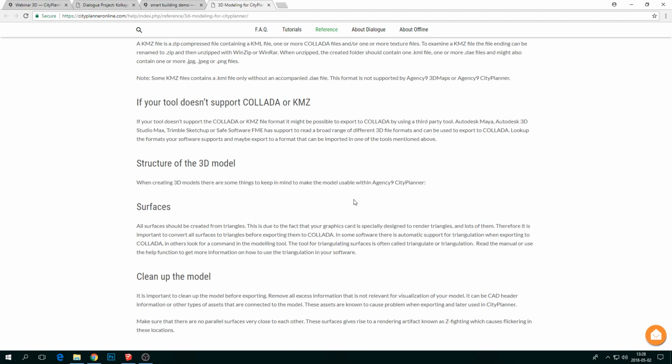So, a quick summary of what we've been discussing, and again, if you have any questions, feel free to ask them in the chat window or contact us after this webinar. We have been talking about reducing faces, removing unnecessary geometry, and replacing those with simple geometry as transparent raster images. Yes, exactly. Make sure textures are compressed so they download quickly, but also limit the resolution of the textures. Otherwise, rendering them will be slower.